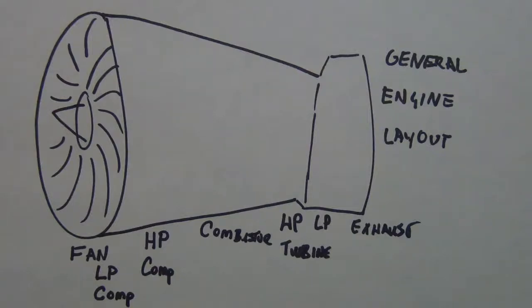The reason it's designed the way it is, think about every part coming from the manufacturer. It's designed to minimize any threat to the function of that system, whatever it might be. In this particular case, we're talking about the engine system, and the threat is ice buildup. When you have that air coming in, it can be very cold air, right? Coming into that air inlet, that cone is specifically designed to at least reduce any ice buildup at that point.